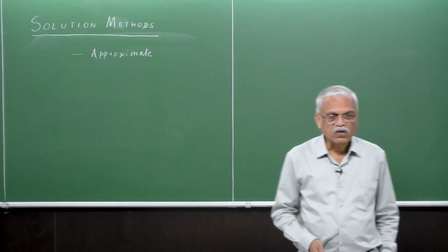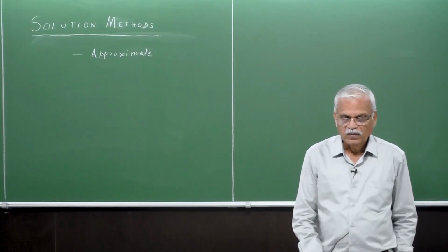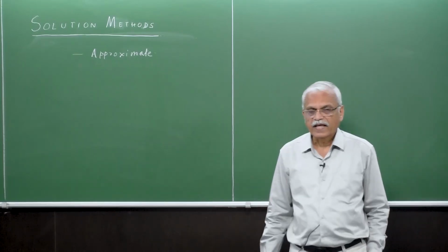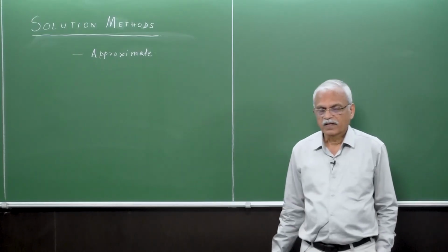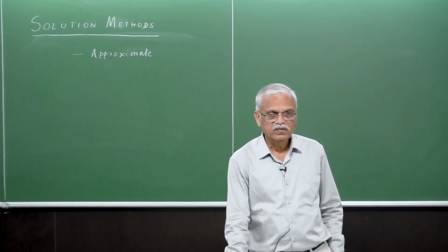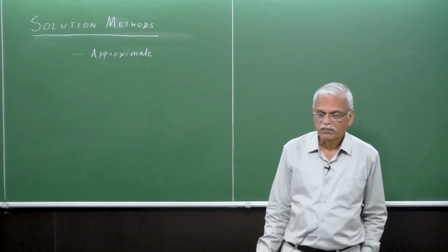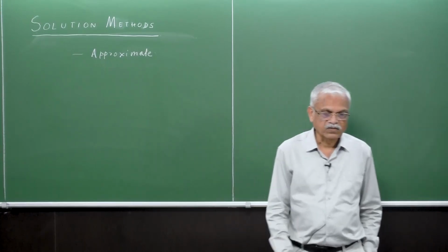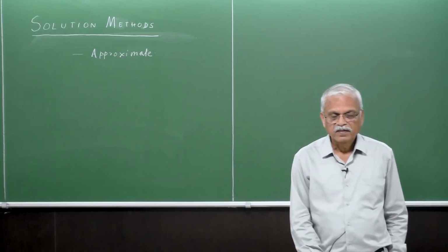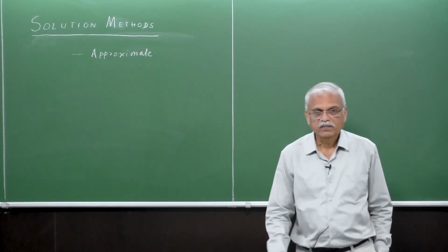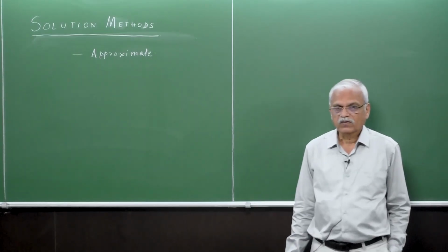So we have talked about three methods. One is the variational formulation, and the other one is the direct differential equation approach. The governing equations are directly given in terms of differential equations, which need to be valid at each and every point together with boundary conditions. And then the third one, I also mentioned, is another method of formulation, that is the virtual work principle. Particularly, it is suitable for solid mechanics.